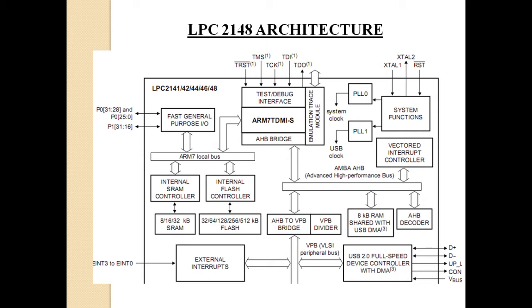The problem is that if you want to write some data, first you need to write in the first register, the first location, then you need to write in the second location. Like that only you can write. So bulk read and write was not possible. That is a problem. So in order to have that advantage, they have developed another type of ROM known as flash ROM. That is the latest one.